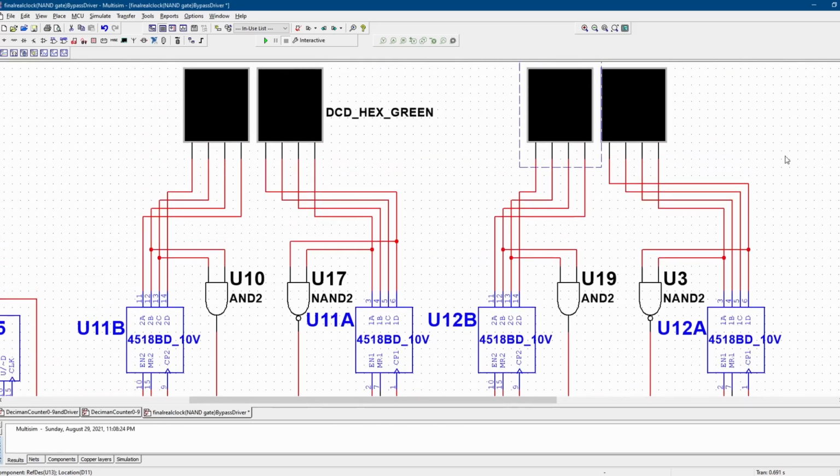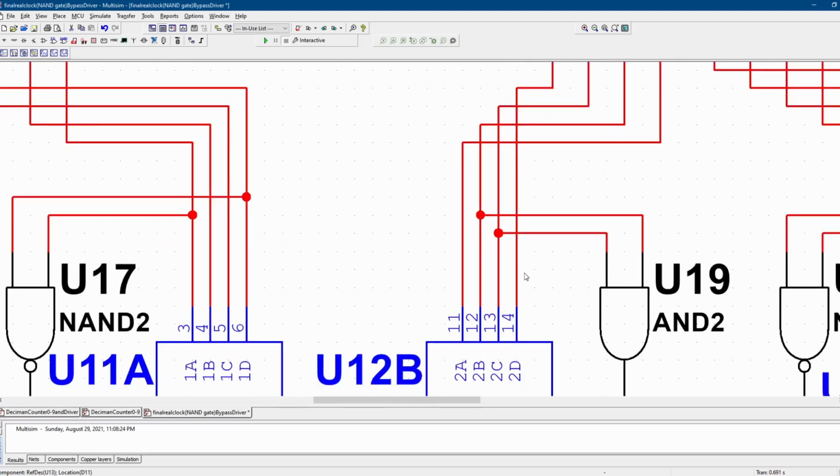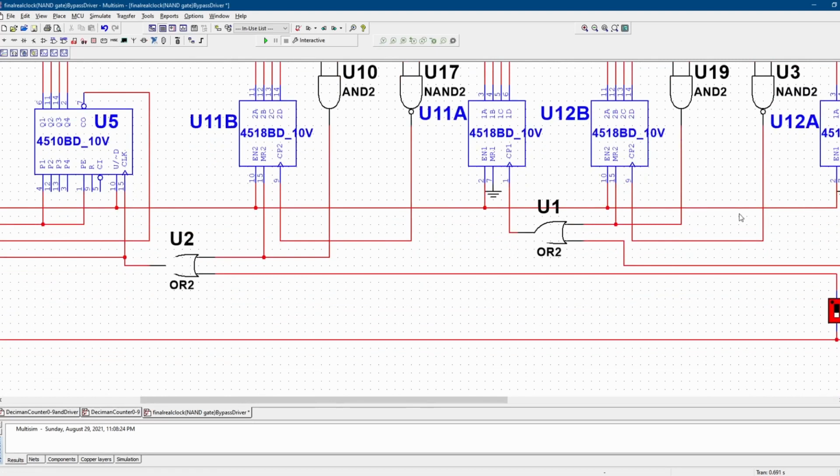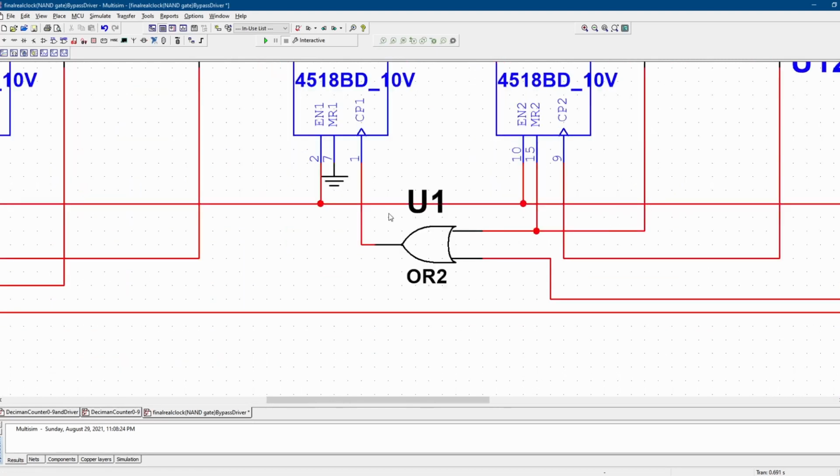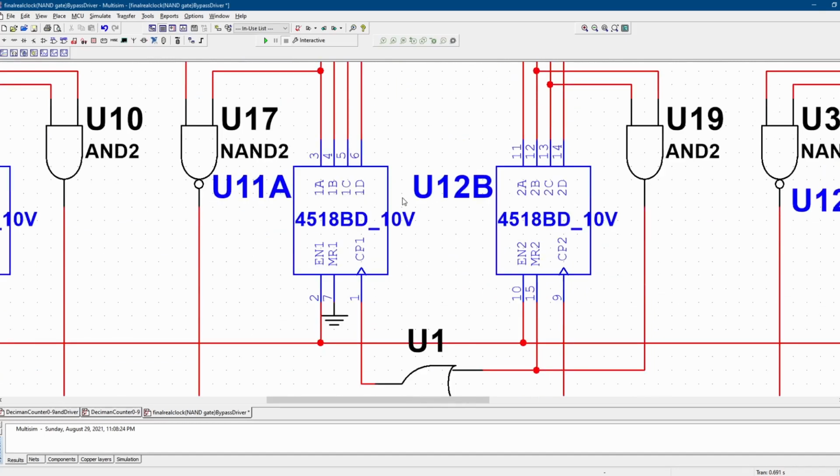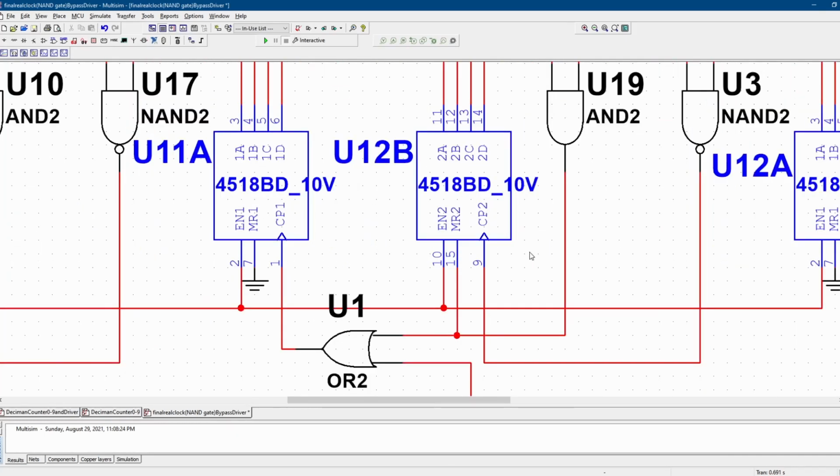One of the things is that this has to go from 0 to 59. So we're going to be looking at the case when this is equal to 5, or rather 6. See here? This is the least significant, followed by the one that follows, and then the most significant here at the end. And this is actually equivalent to 6, I'm sorry. So at that instant, when it reaches 6, it triggers a clock. And not only that, it triggers a reset. See here? Triggers a reset.